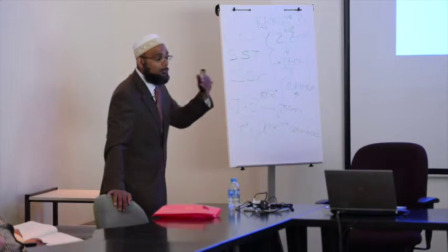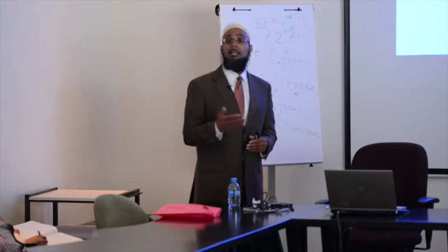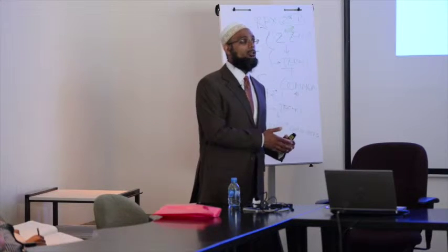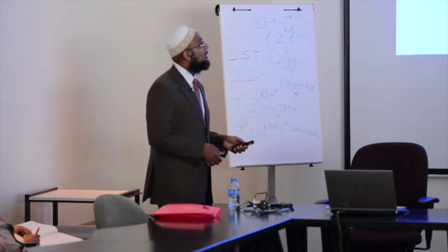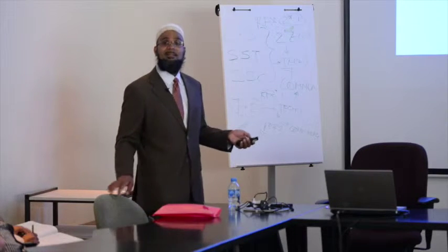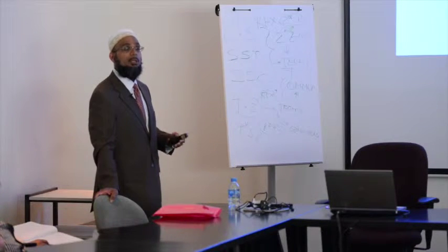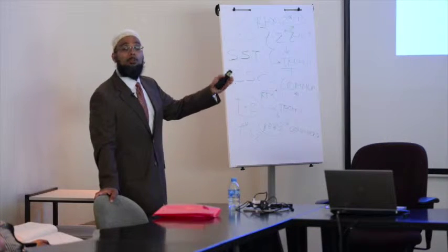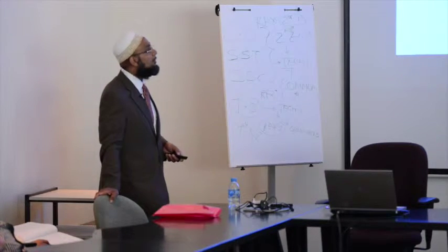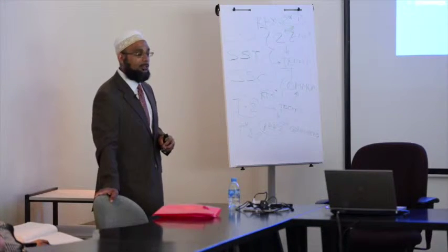Then, since you have high perm zones, they produce a lot of fluid, and after some time they become depleted. So you have mature reservoirs, mature flow units, next to flow units at higher pressure, which are tighter. And the challenge is, how do I place acid into the tighter zones, which normally still have a lot of reserves, and not inject into the depleted reservoirs, which could be producing water and increase my water production, right? So these 3 challenges are mostly for placement of acid.